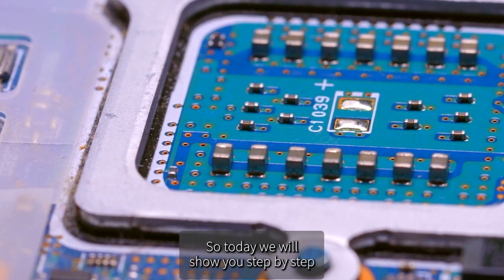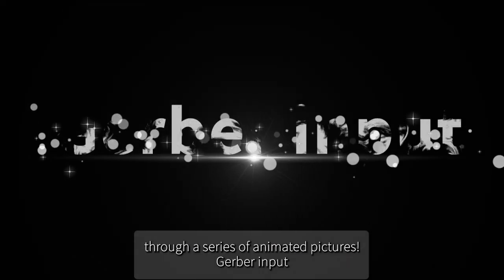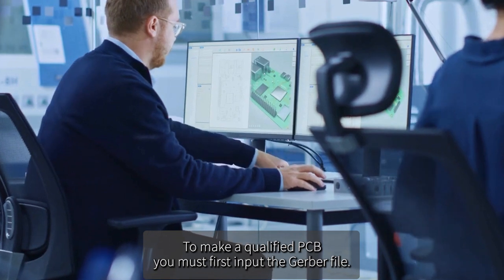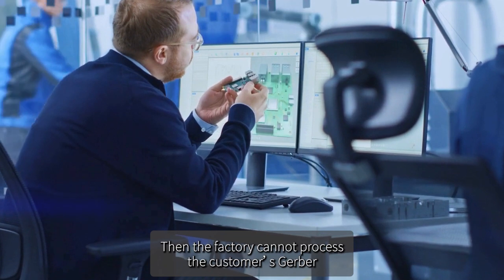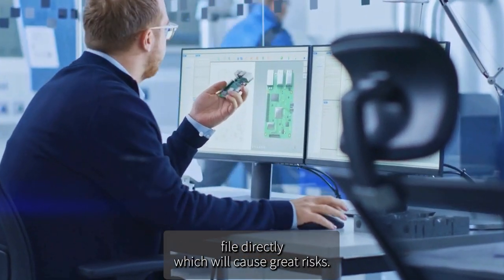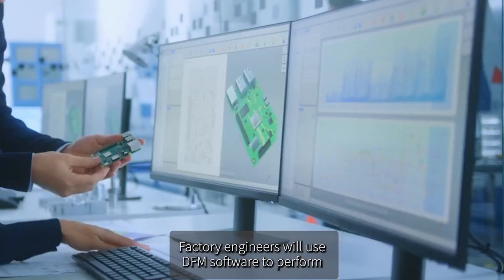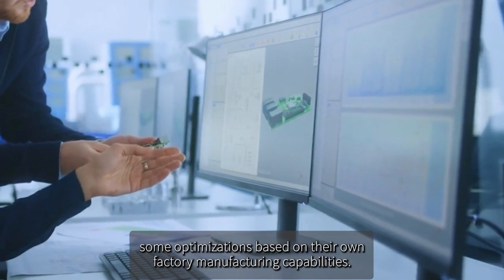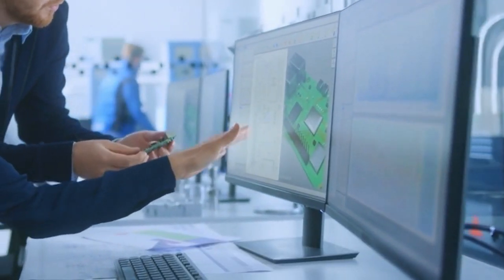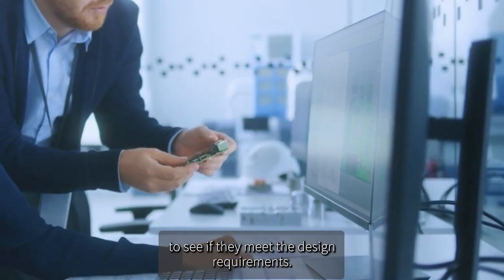So today we will show you step by step through a series of animated pictures. Gerber input. To make a qualified PCB, you must first input the Gerber file. Then the factory cannot process the customer's Gerber file directly, which will cause great risks. Factory engineers will use DFM software to perform some optimizations based on their own factory manufacturing capabilities. Of course, the optimized parameters must be communicated with customers to see if they meet the design requirements.